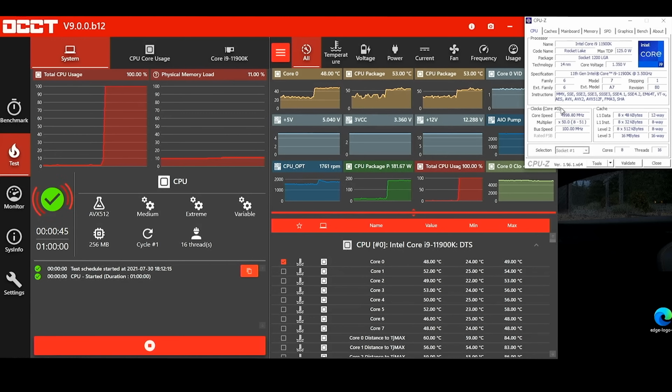So again, you can see because we do have AVX going on at the moment, that's sitting at 5 gigahertz. Our core voltage is sitting at 1.35 volts. Again, we do have that little bit of droop because of the amount of load that we have on the CPU. So we probably could actually push that load line calibration a little bit higher and push those cores a little bit higher if I really wanted to, given that our temperatures are well within our safe range at the moment.